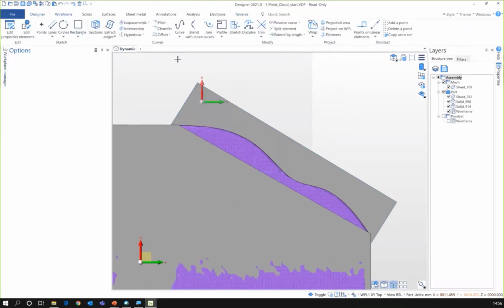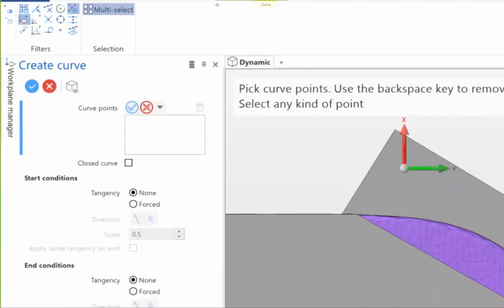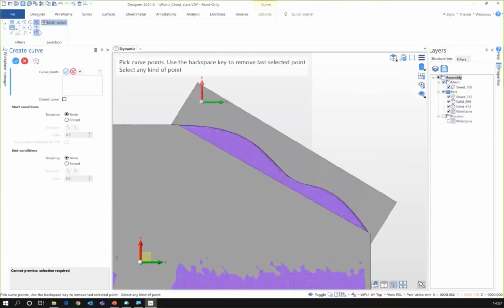I'm going to use a wireframe curve and turn on, so this is something that is worth noting, these little filters here. We're often working on the enhanced pick, but sometimes it's nice to have more control. But also we can use the options alongside these picking options. So that is our project onto current work plane option. It's another one to remember to turn off as well.